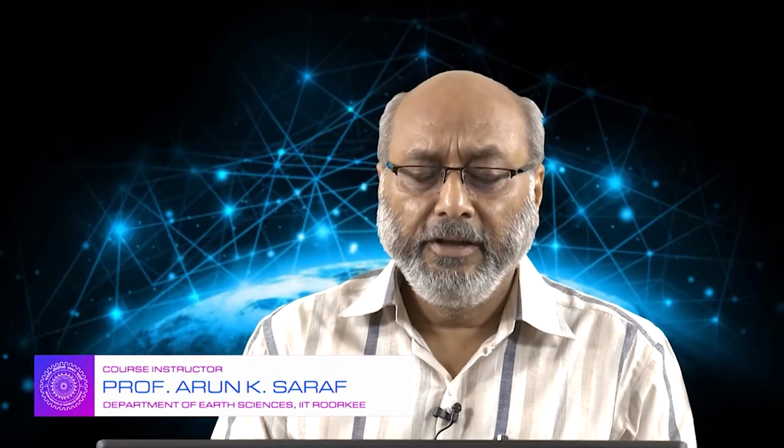Hello everyone and welcome to this discussion, which is the second part of our spatial interpolation techniques. In the first part we discussed interpolation up to the linear one. Linear interpolations are not that popular, but sometimes for certain requirements one can definitely go for them. Those options are available in the software, and one can even go for Thiessen polygon. One can create Thiessen polygon, but it is an old method from when we did not have GIS software or any such software. Then people were only resorting to Thiessen polygon.